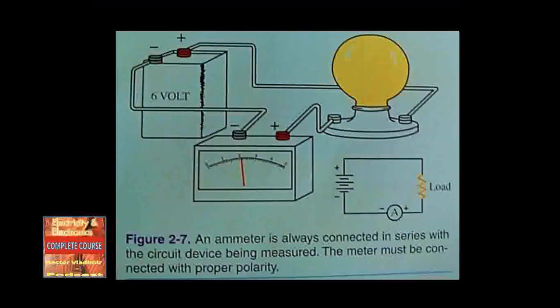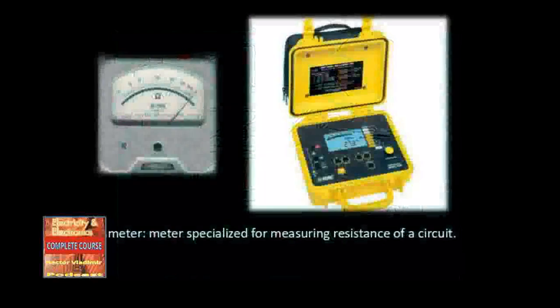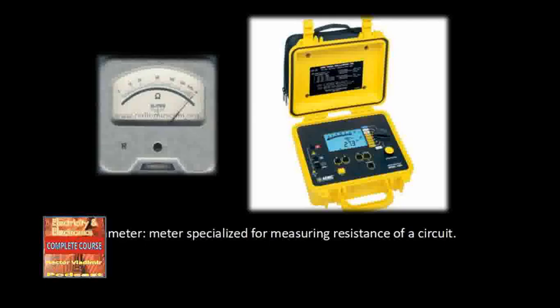When measuring current, an ammeter must be connected in series with the circuit. A wire must be disconnected to insert the meter. It is wise to make a rough current calculation using Ohm's law to determine the proper current range on the meter. When troubleshooting a circuit, it is best to start on the highest possible setting. A faulty component can cause higher currents that would not be normally expected. Again, observe correct polarity, red to the positive side of the circuit and black to the negative side of the circuit.